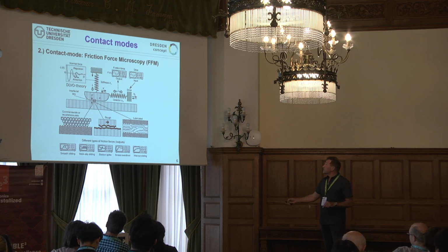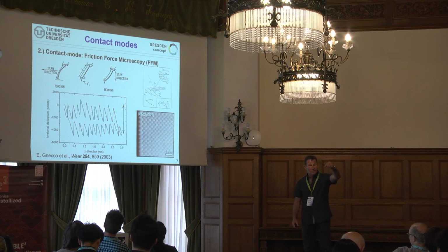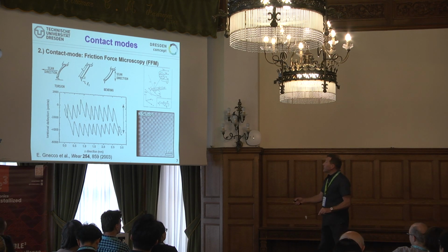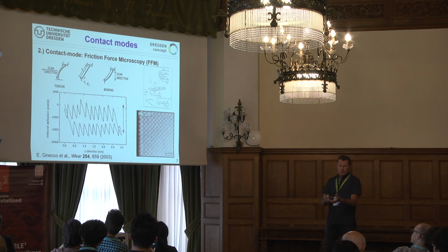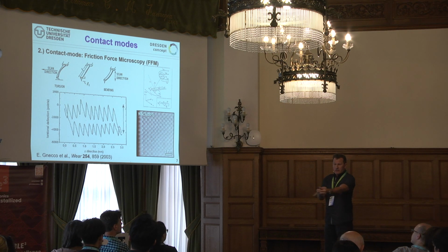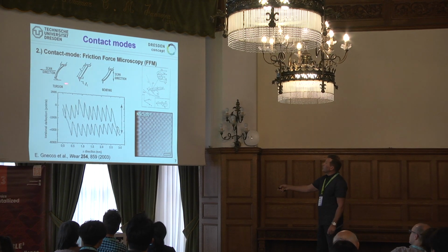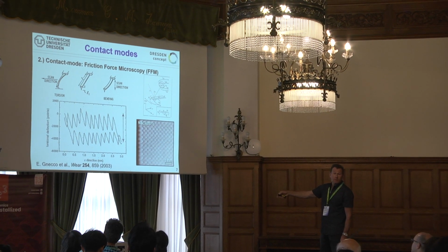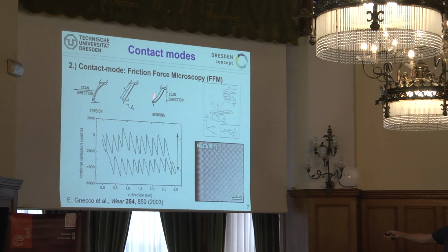Now we can translate this mimic to the cantilever, because as we said already, we have a K constant vertically, right? But the same way we can also use this kind of torsional mode. So I can take this cantilever and you see it, and I can twist it actually very heavily in this way, which means we do the same mimic, the same calculation, okay, different coordinates, and we calculate the resonance mode of this one, which is typically about 9 to about 10 times higher than the bending mode.